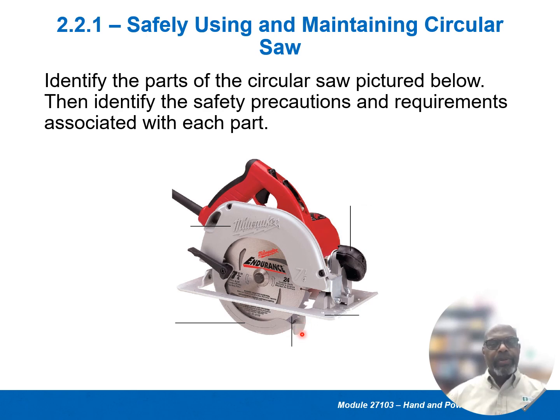The only way this can open is when you put the fence completely down and you push. This will get pushed back as you push your saw through the wood. As soon as you finish, it pops back. It's spring loaded. Yes, you can lift this handle up here to start it. Sometimes you have to, unless you're starting in the middle of a piece of wood, you can't push it through. You have to start it someplace else.